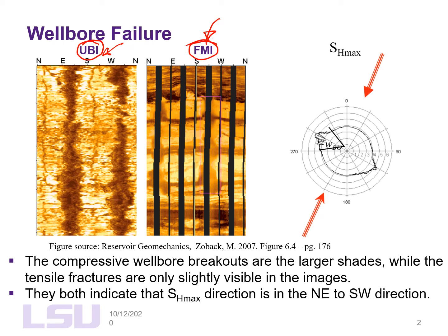The fatter one, as you can expect, is which one? Wellbore breakout or drilling induced tensile fracture? Just from what you had seen on the previous slides, where the wellbore breakout was wide, whereas the tensile fractures were very thin, right? It's a very small scale fracture created in tension. So the wide one is your wellbore breakout. So this is your wellbore breakout. Same here.